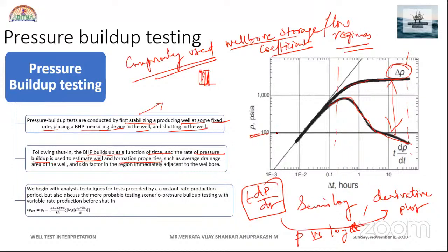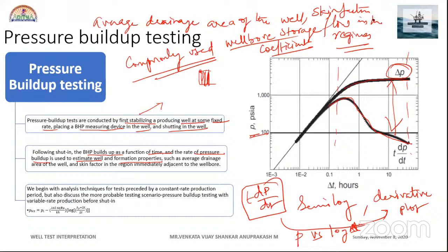So from the build-up test we can get the average drainage area of the well and the skin factor in the region immediately adjacent to your wellbore.